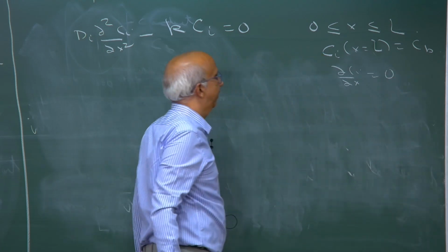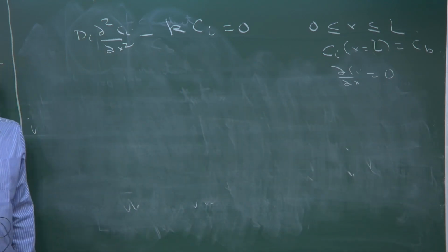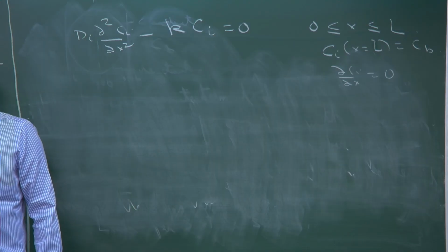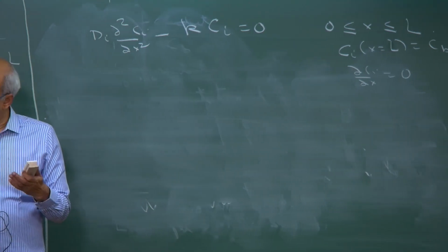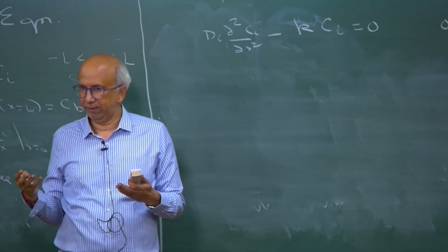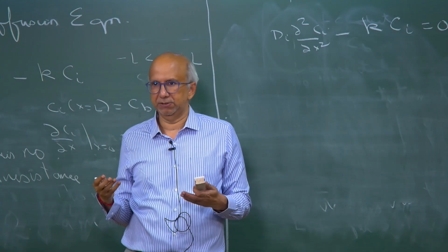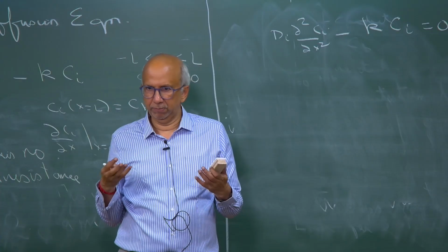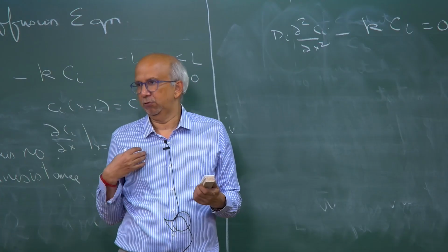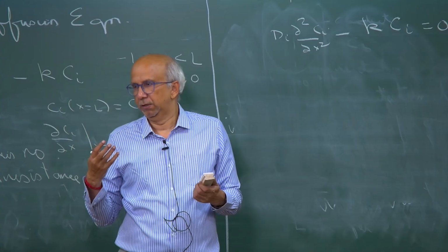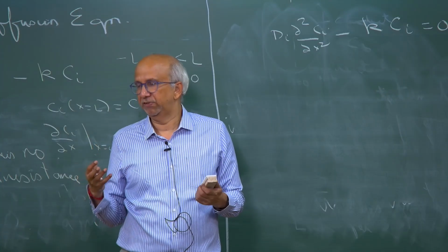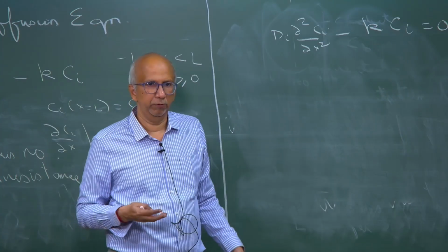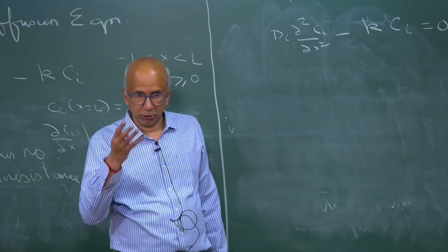Same thing I have written again, but I am going to make it dimensionless now, because I am trying to compare two things, reaction rate and internal diffusional resistance. When you are trying to do a comparison, you need to make it dimensionless, because there is no point in me telling you the rate is high or low, with respect to what, right.